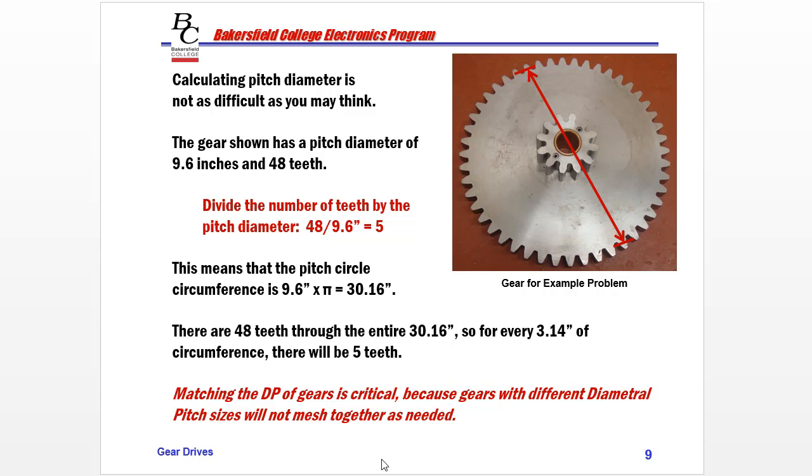And with a big difference in diametral pitch, you can just hold the gears and try to push them together by hand and turn them without being on the shaft, and you'll totally recognize that they won't turn at all because the teeth don't even line up and mesh.